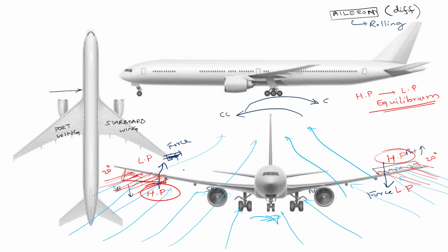One is lifting upward. Just imagine this aircraft is fixed and it is moving, and one wing is trying to move upward and the other wing is trying to move downward. Now gradually it is moving and this is going up. Which side is it rotating? In this particular phenomenon, from your front view perspective, the aircraft is going to make a clockwise rolling motion.